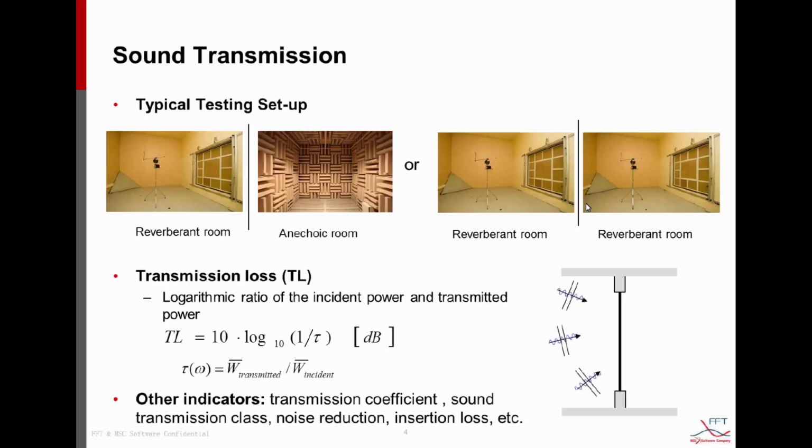In both cases, in the left room, there will be an intense acoustic excitation injected through the speakers, and due to the reflection of the rigid walls, a diffuse sound field will be formed and applied on the object, which will induce vibration of the object, which consequently transmits acoustic waves to the other side of the room.